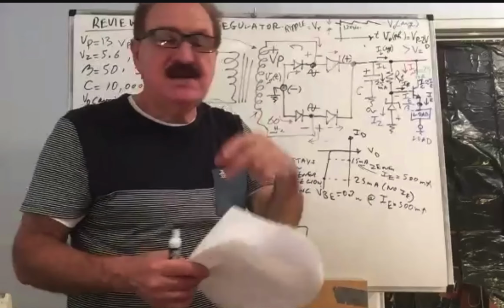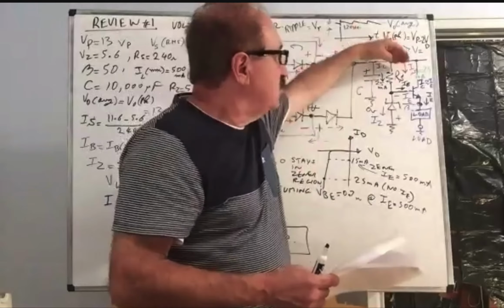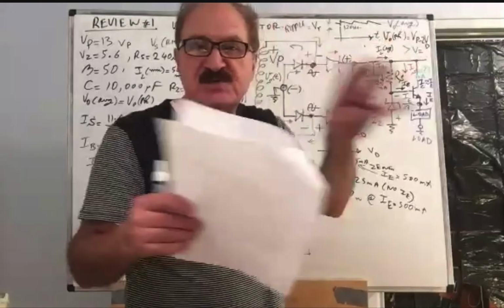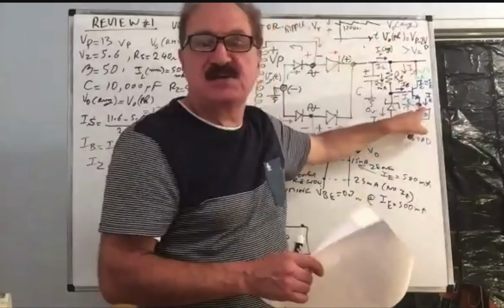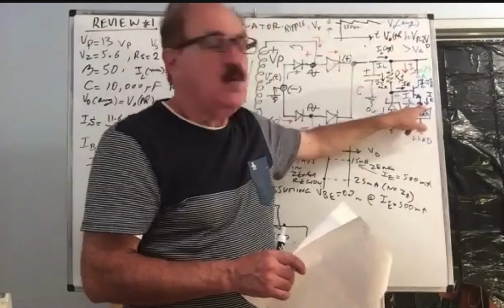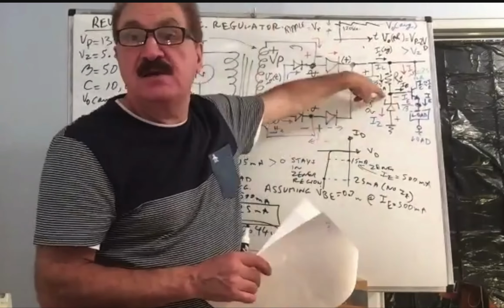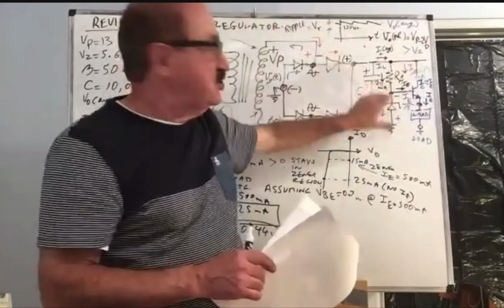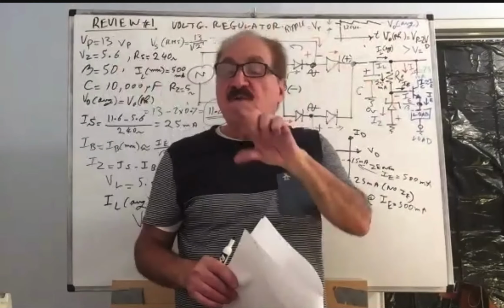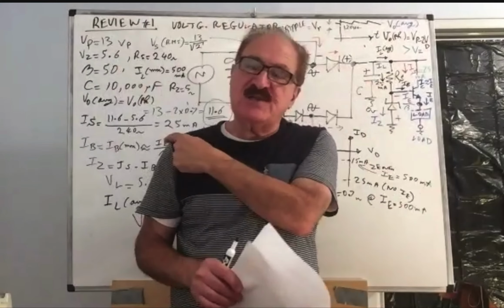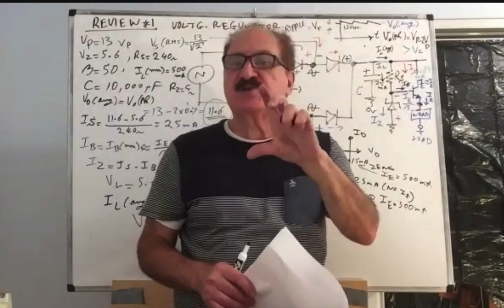But again, I stress that fluctuation of 1 volt will never see light in here. You never see it here. Why? Because that emitter voltage is following the Zener voltage, and the Zener is almost free from ripple for the reasons I explained. Their dynamic resistance is very small.